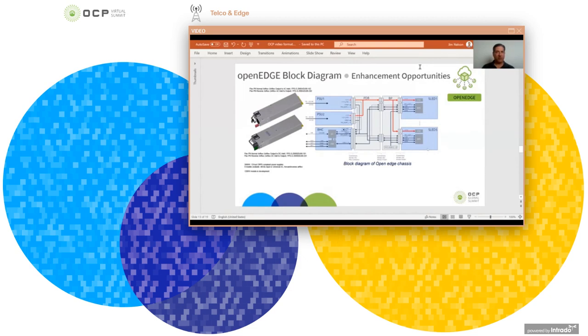That's the place where everything that's required in the sled for the processor, for example, if it needs 5 volts, 3.3 volts, 1.8, 0.8, whatever the lower voltage requirements of the sled are handled with the PDB. So the PDB takes the 12 volts from the power supplies, either passes the 12 directly to the sled for the uses that require 12 volts, or if there's specific lower voltages required that the PDB has generated, it's able to pass those over to the sled.